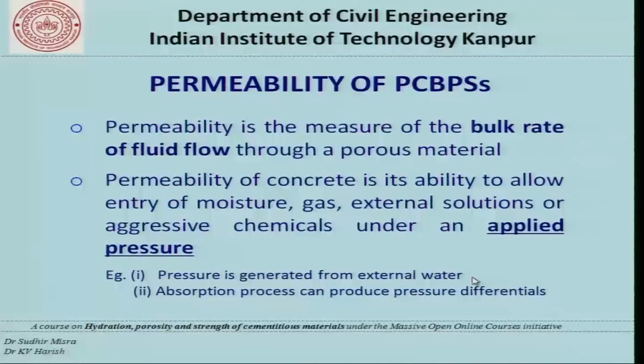If you take dams or other cases, you see that huge water is on one side of the dam, and remember that we are talking about a concrete dam. So the water is usually present for a longer time, and the hydrostatic pressure of water will provide the pressure that is required for water to penetrate into the dam. So here example 1 indicates the case that happens in a dam. Pressure is generated from external water. Sometimes you may also have an absorption process that can produce pressure differentials.